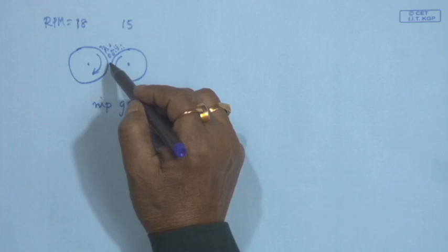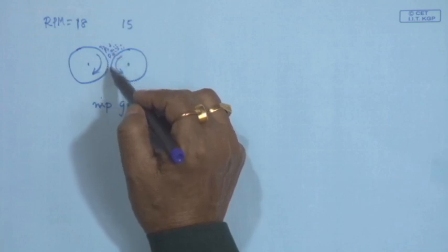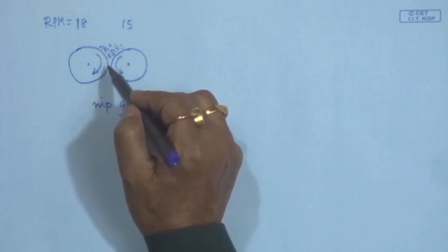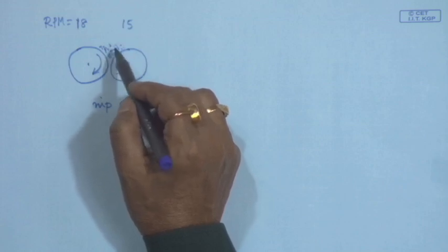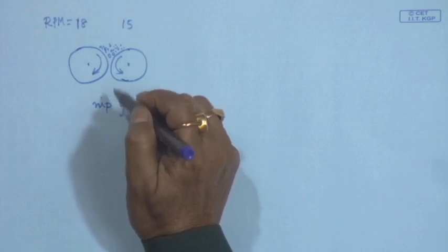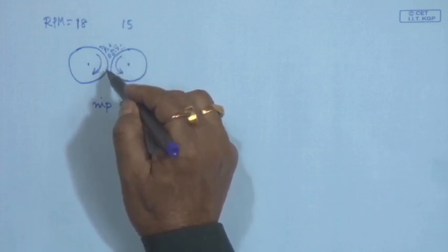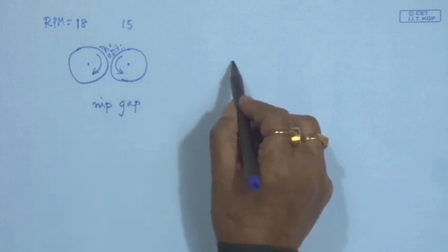So, at any instant of time one roll appears to be stationary to the other roll, and that provides the shearing action over here. That shear action breaks down the molecular chains of the polymers, and it generates heat which makes the polymer soft and decreases the viscosity. So, by this principle we get a mixing of these component polymers in a two roll mill, and the internal mixer is a variation of this open mill.